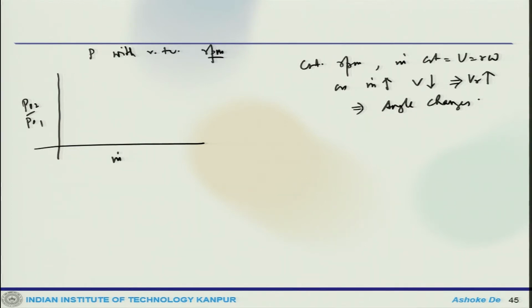Okay. Now, the first thing that could happen is that the valve is closed. When the valve is closed, the m dot would be 0, so this is a situation where m dot is 0, and P naught 2 by P naught 1 would be A, corresponding to the centrifugal pressure rise because of the impeller on air trapped between the vanes.